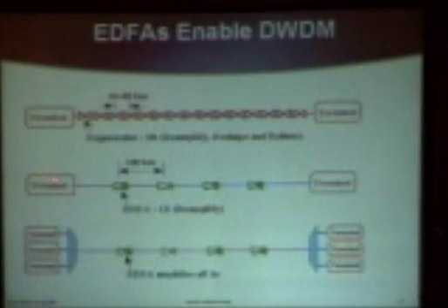So then in the early 90s, some bright physicists came up with the ability to make an optical amplifier. This amplifier was only a 1R amplifier. It did not do the reshape and retime functions, but it did compensate for attenuation in the fiber plant. And these became very popular, mostly because it turned out you could space them every 120 kilometers. So you had a lot less equipment, and the equipment tended to be a little bit more reliable than a regenerator because its functionality was lower. So the ground was set.